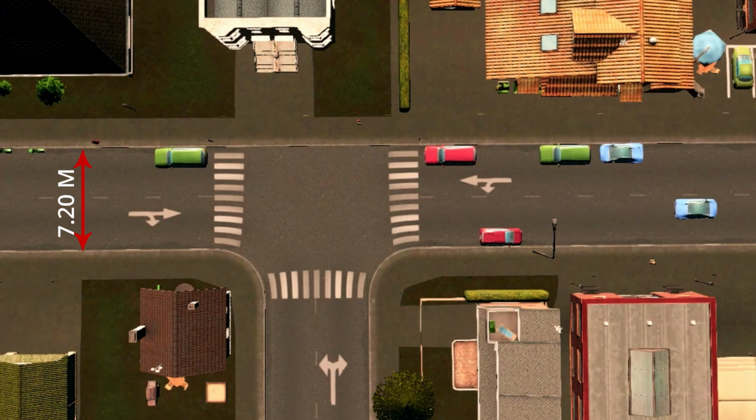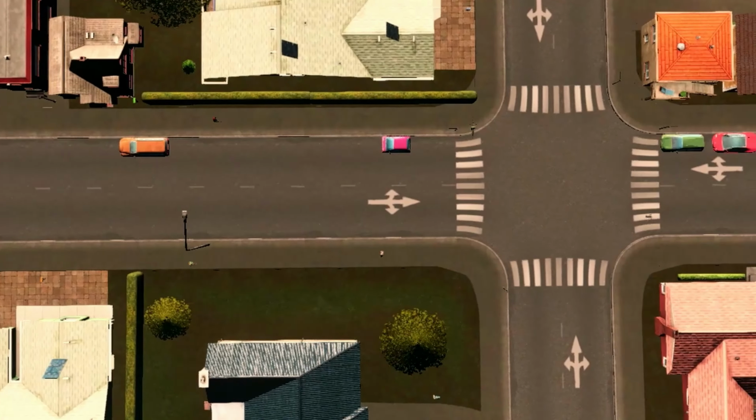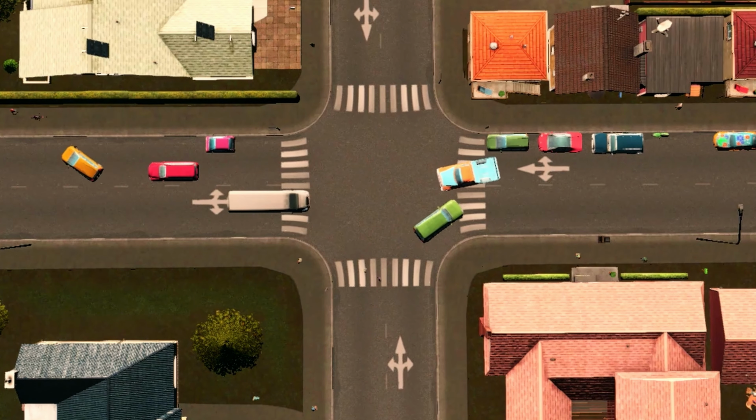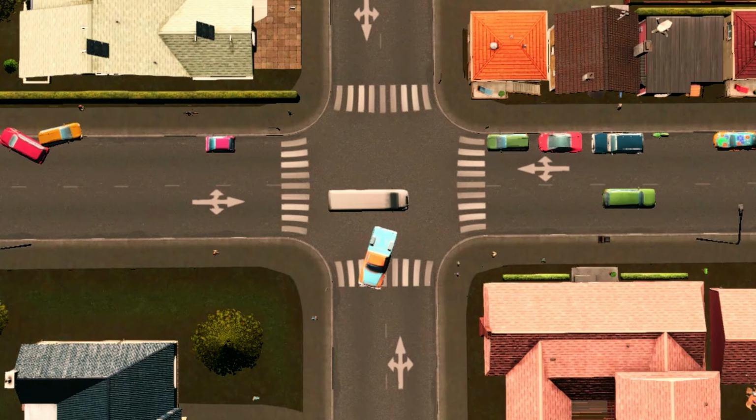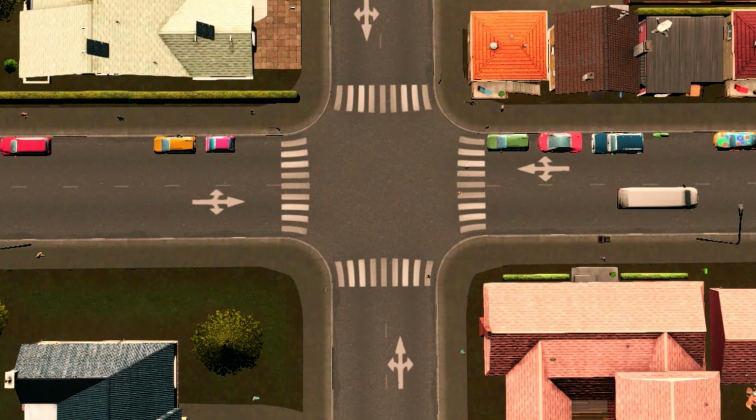The design service volume represents the maximum traffic that can pass safely and efficiently through a highway section while maintaining acceptable driving conditions. According to IRC recommendations, a standard lane under ideal conditions may carry approximately 2,000 passenger car units per hour under uninterrupted traffic conditions. However, in real-world highways, capacity reduces due to heavy vehicles, side friction, intersections, terrain, pedestrian movement, roadside activities, and access points. Therefore, actual lane requirements must be adjusted carefully.